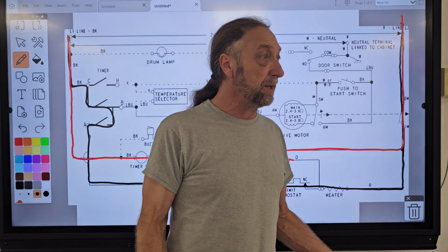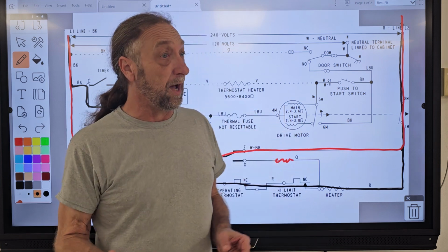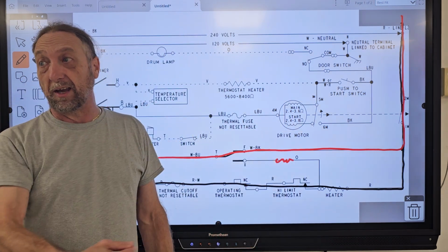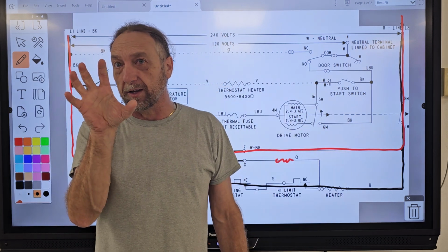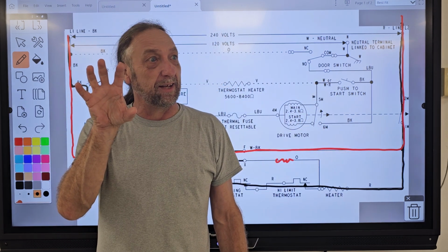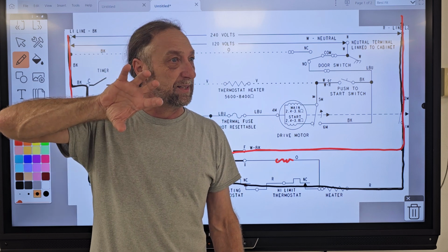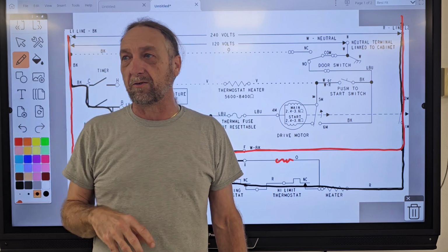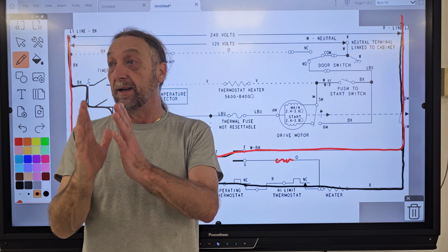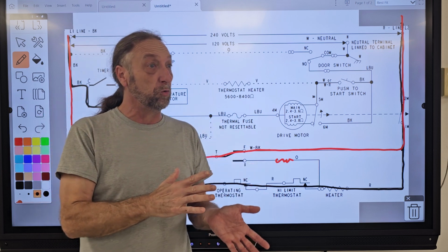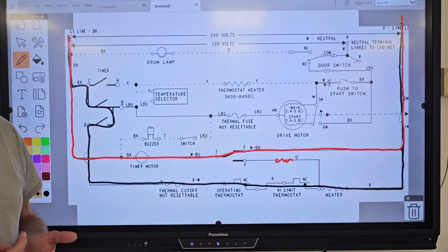Maybe not 5 full minutes, but at least see if the timer advances. Now one thing about timers is they don't advance like a second hand on a clock where you can actually see it moving. They move like click, and then they sit there for a minute or two before they go click. They move in very small increments. But it is noticeable: you could put it in a spot, wait 2 minutes, and see if it moved. And that tells you already have voltage, okay?